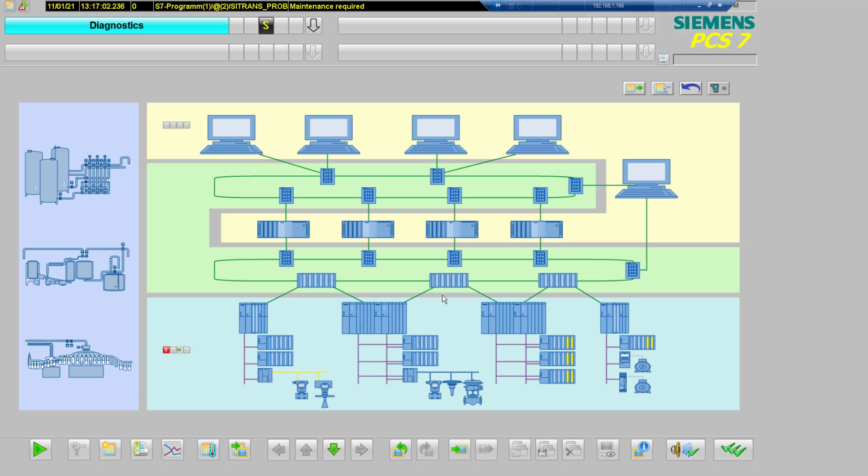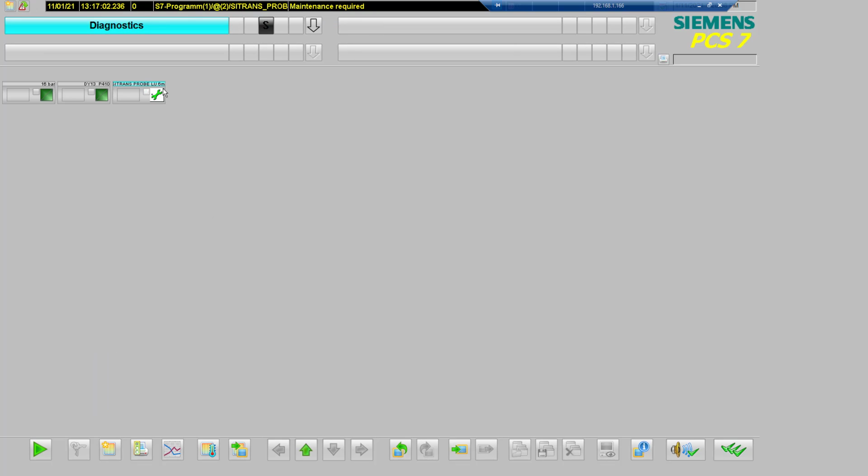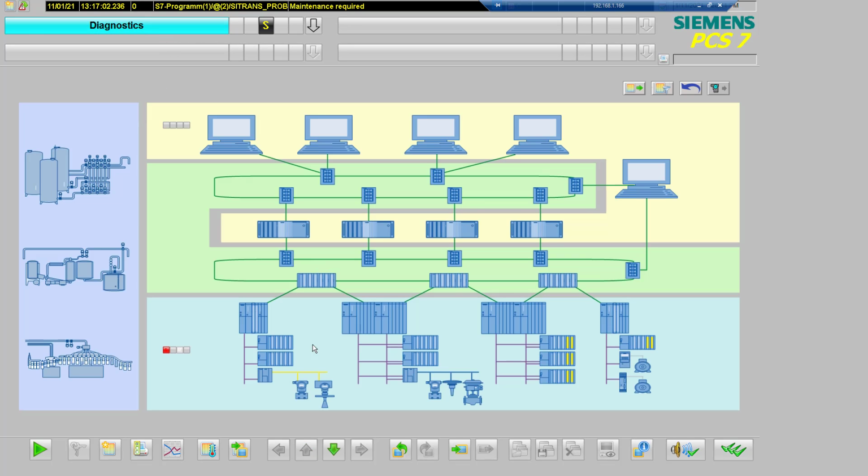To make sure that PDM Maintenance Station is working, go on to the Diagnostics tab, because that's where all the functionality is contained, and you'll see these icons, and you'll see your alarm banner as well, so you can use the loop button to loop to alarms. So if I just go back to the diagnostic screen, if you see any of these with a white cross, that means that you haven't downloaded the CFC into the PLC, so you haven't got that side of communications. So if you've got any errors, you should see these. If you've got no errors, this will all be grey and there'll be nothing in the alarm banner.